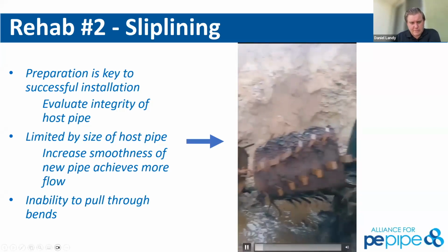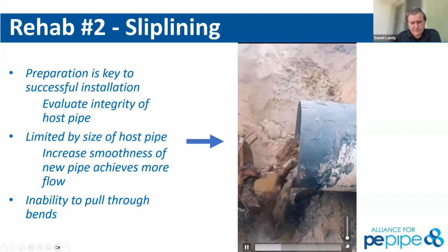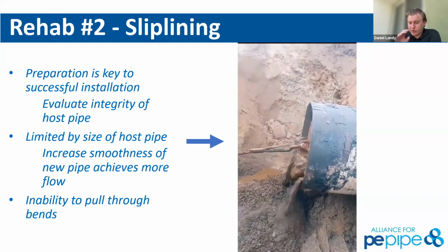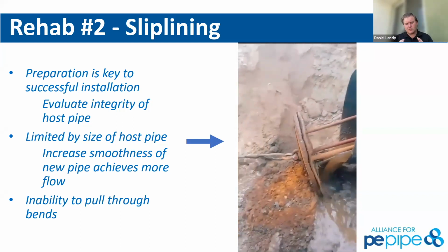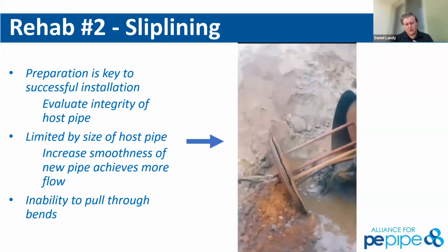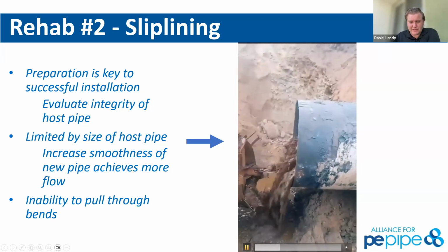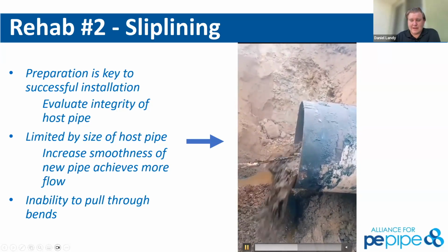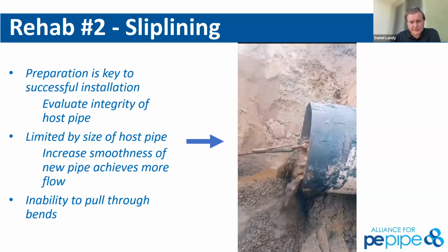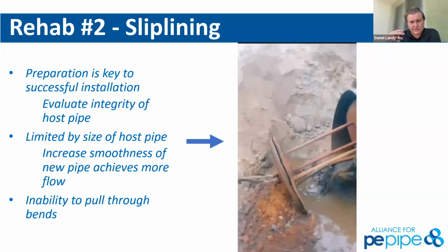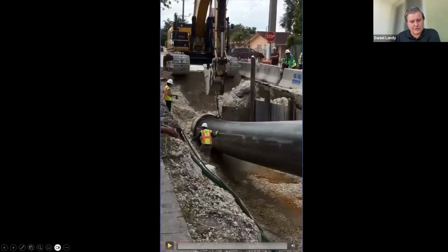The one thing I wanted to mention, the main concern when we're starting to look at slip lining and compression fit, is assessing that pipe, really finding out if there's misaligned joints, proving out that ID, making sure we don't have any oval areas where if we slip a new pipe in, it's going to get stuck, and we have to reduce the ID of the new carrier pipe because of that. So I know it can be difficult to go ahead and CCTV it, especially if it's a non-redundant line. I know 3D technologies and scanning are becoming popular, but this is definitely good information you guys want to get early on in your project and your feasibility studies, so you have a good understanding and don't spend too much time working on a project that's not going to be able to be completed.